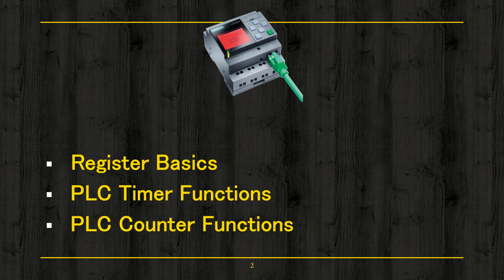Now, whenever we talk of a particular PLC, of a particular model and make, the memory is completely dependent on that particular make or manufacturer. Therefore, while programming a PLC, you should get into the details of the memory map invariably if the program requirement is complex. Otherwise, you will put yourself in trouble.